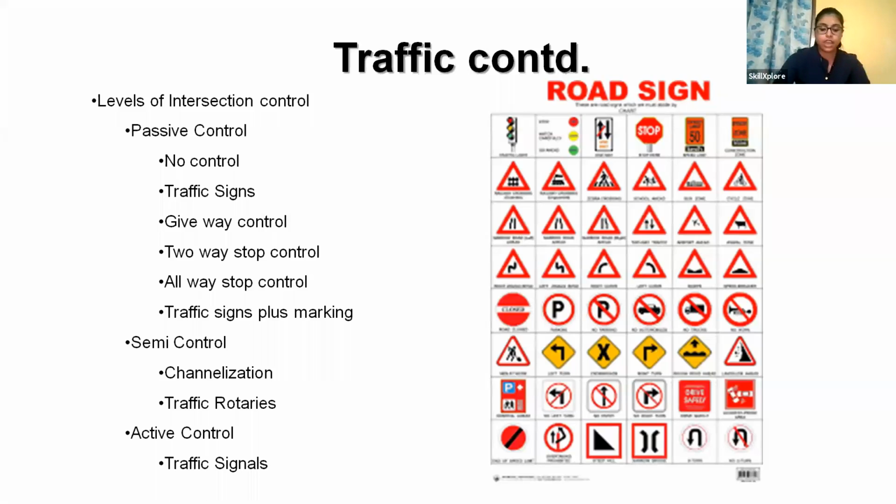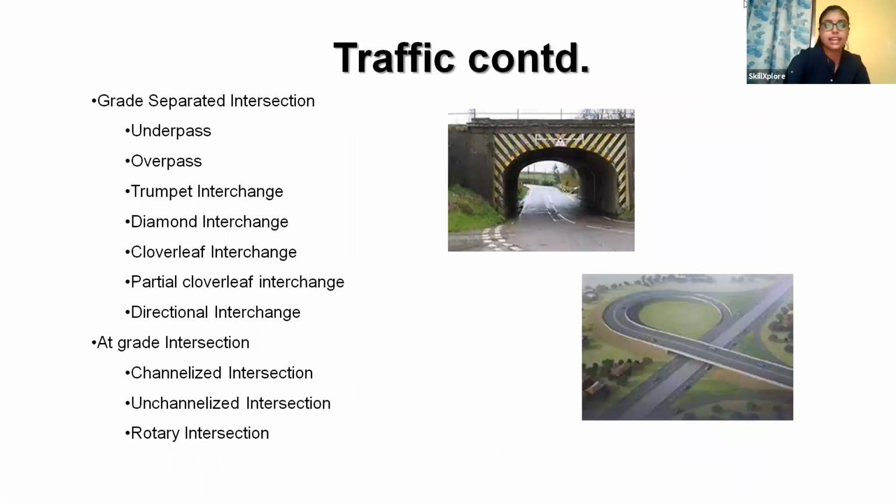Again, give way sign. The give way sign is used to control the vehicles on a road so as to assign the right of way to traffic on other roadways. This sign is triangular in shape with the apex downwards and a white border. So all these things we have to understand. It will be in white color with a red border. This is apex downwards, not apex upwards. 4 options will be there, and it might get confusing. So all these things we have to study separately. These things will be addressed.